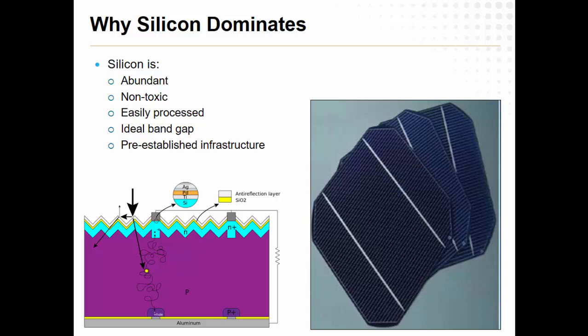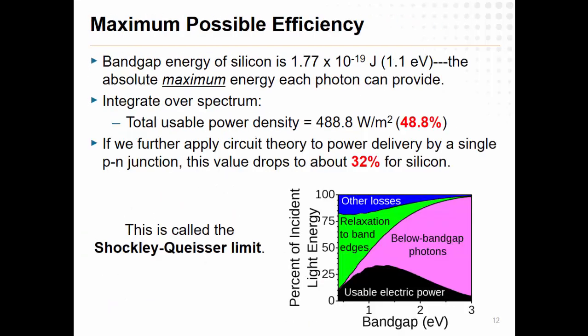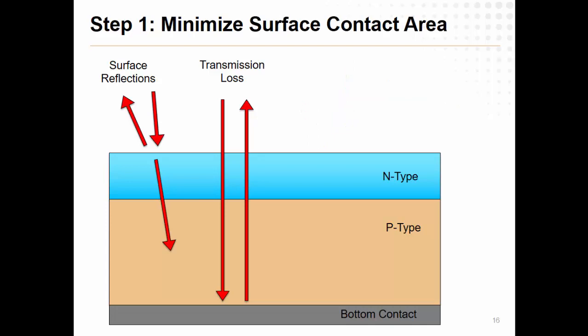You have to keep a reasonably good coverage over the thing, or else an electron hole pair event over here is going to have to wander over to that contact eventually, and if it's too far away, they just recombine. So you have to have very strong coverage. There's kind of competing factors there. You want to collect your electrons and holes, but you don't want to block the light from getting in. So a lot of smart people have probably figured out that balance as well. So you do your best to just minimize the contact up top.